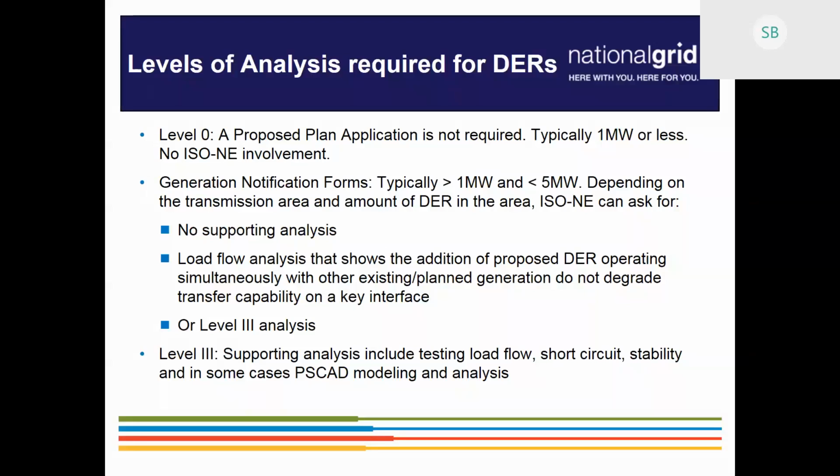No, there's no upper limit. As a matter of fact, the higher you go in site size, the more likely it is that you're going to need that recloser there. It becomes more of a requirement as you increase the size of your site. There isn't necessarily a lower limit anymore either, because in certain instances we require it specifically because of site size. So 1 megawatt and greater absolutely has to have it. Lower than that, it may be required in order to avoid things like DTT or other requirements, to avoid risk of islanding.